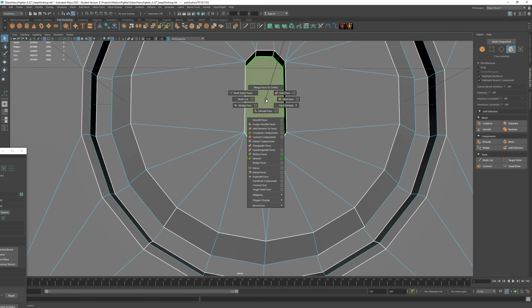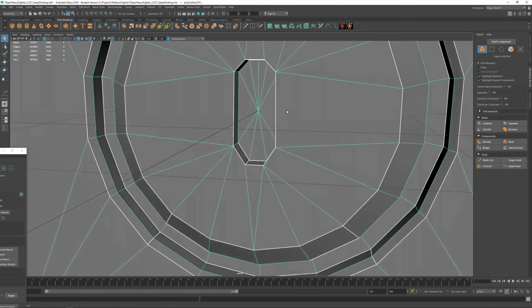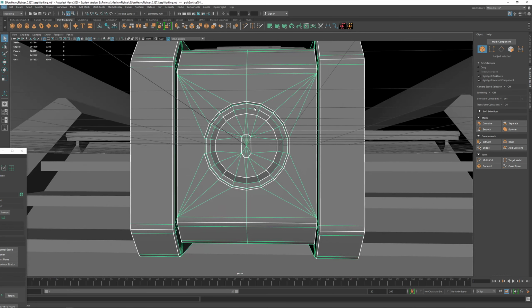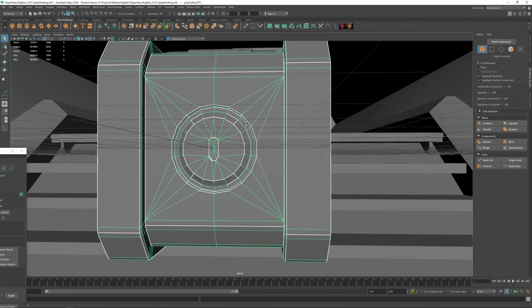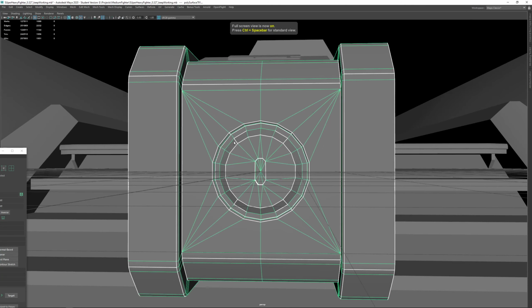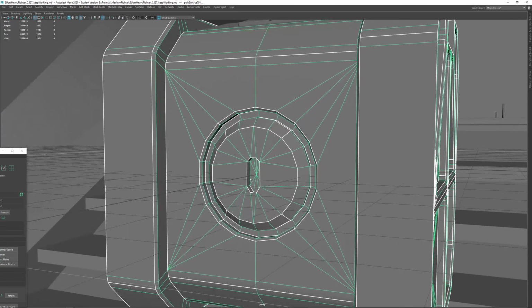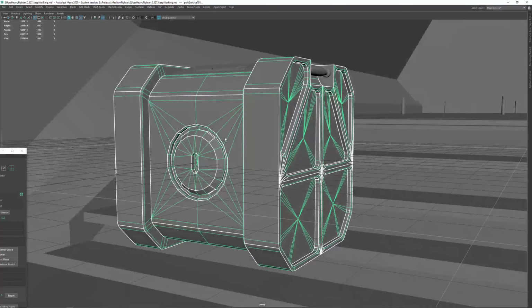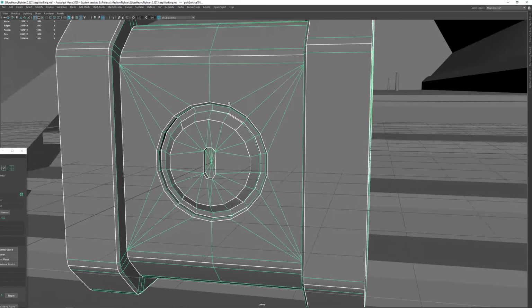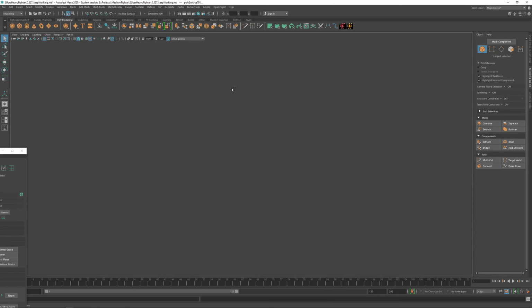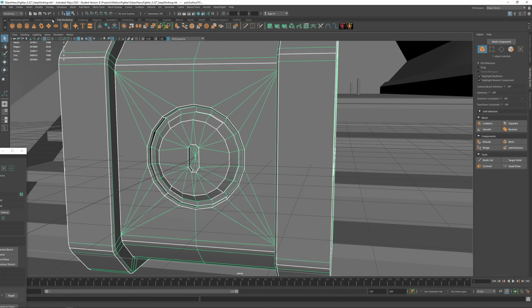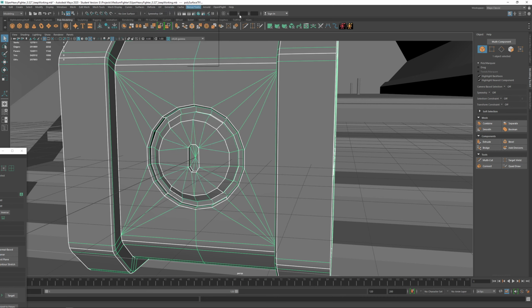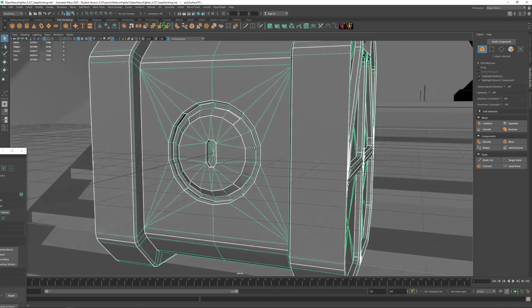and select the face and poke it. Shift right click to poke. Yeah, I always use shift right click, and you can use Control spacebar. Control spacebar, and that is called pro mode. So most of the time, just maximize your space, because you're using shift right click and you don't have to go here in the poly modeling, going through all these menus, it's a lot of them, or just going right here on the right.